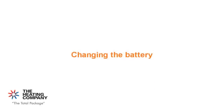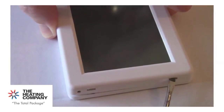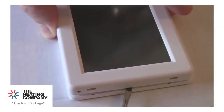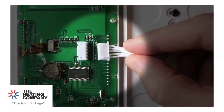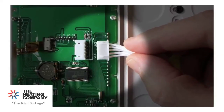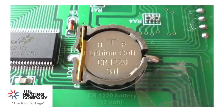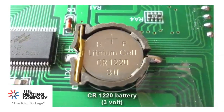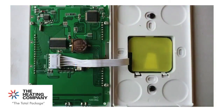Changing the battery. To change the battery on the thermostat, use a small flat-headed screwdriver to pry the unit away from its base in 2 places below the unit. Then turn the unit over and remove the ribbon connector for easier access. Gently pry the old battery out and replace it with a new one. The unit uses a TR8100V 3V battery. When the new battery is in place, reconnect the cable and clip the unit back into place.